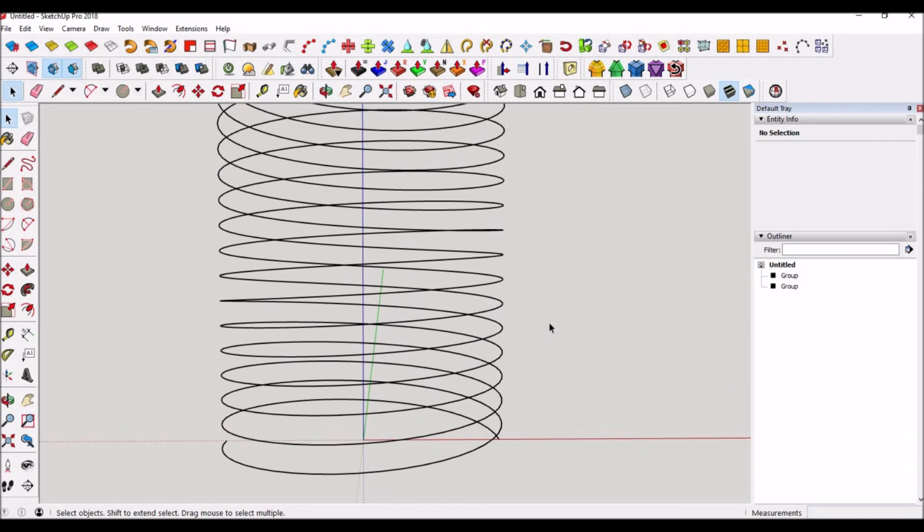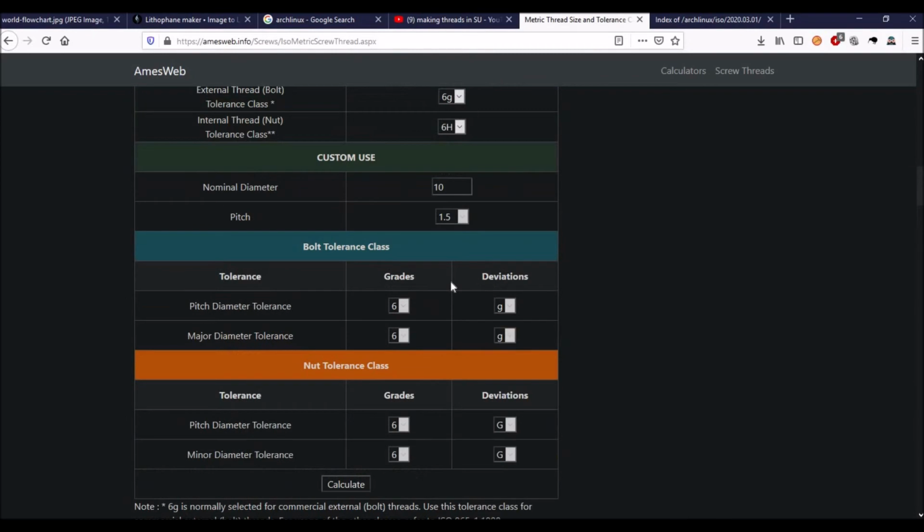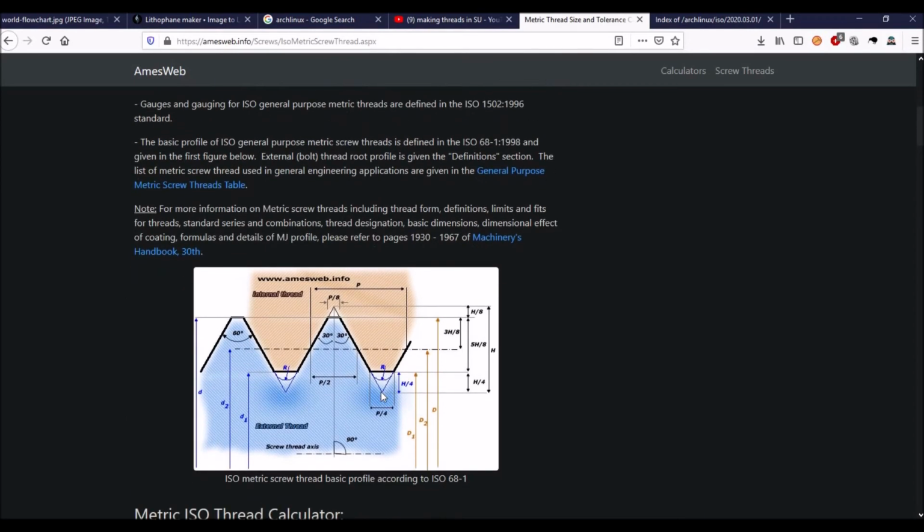So now, we'll notice what pitch is from here to here. So that's 1, but now it's a half. And now you're wondering, okay, well, Matt, you just told me we needed a pitch of 1. Now we've changed it to a half. So what gives? Well, this one right here in the center that I have highlighted is actually going to become this one right here. We're going to squeeze it in, and that's going to become our inner minor diameter.